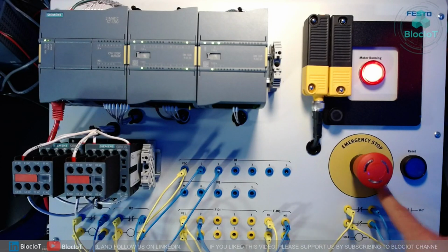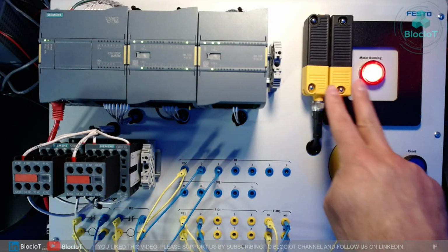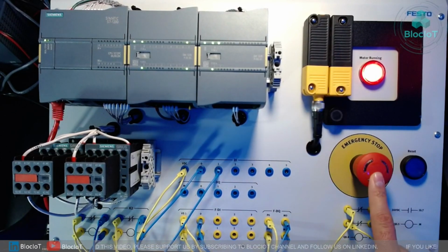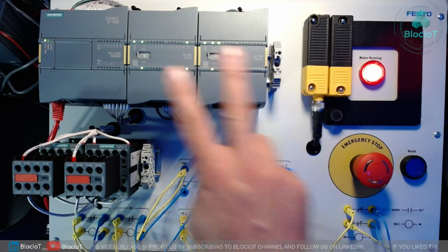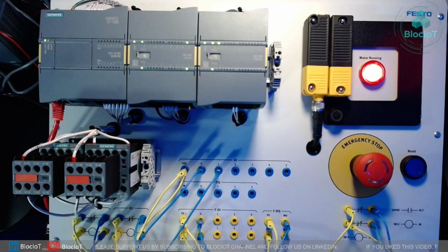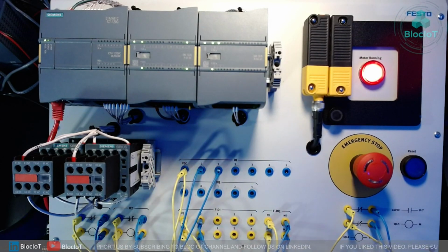And on the lower right, we have the emergency stop button, and also a reset button to acknowledge any fault and alarm. And on the left side, we have 2 relay contactors by Siemens, and these are 24 volts. So in other words, we wired the inputs in the system, which are the sensor, emergency stop, and the reset button, to the PLC, and also the outputs from the safety output card are connected to the relay contactor. And these are just the wiring, as you see here.